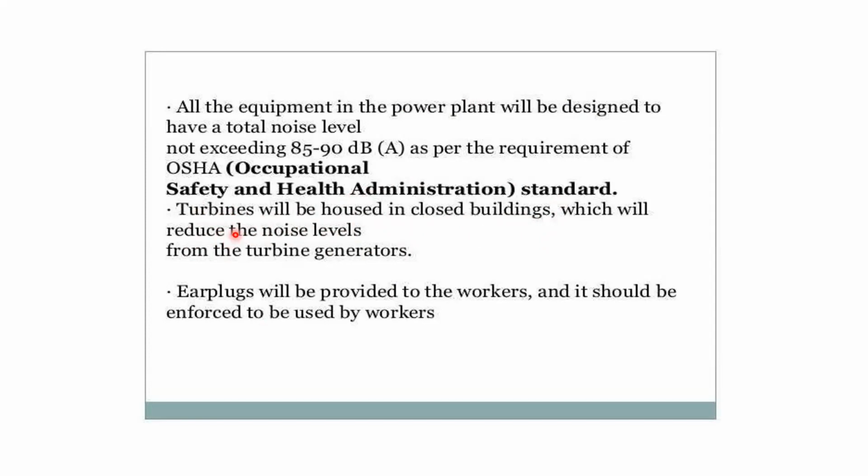Earlier we worked in 210 megawatt plants and also saw 330 megawatt plants where the turbines were housed in open space, or they were open. So what was happening? The noise level was much more because of the high pressure steam entering into the turbines and due to the rotation speed. The rotation of the turbine is also 3000 rpm, so a lot of noise was there.